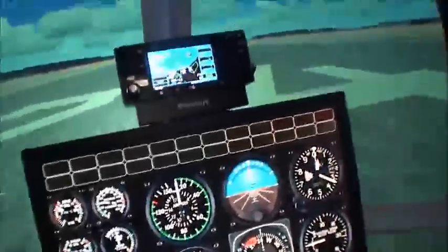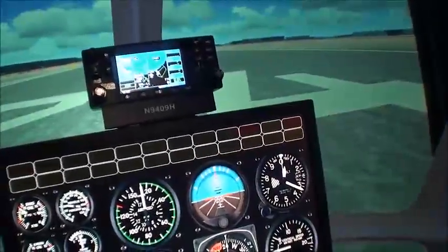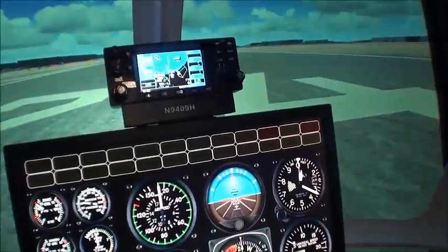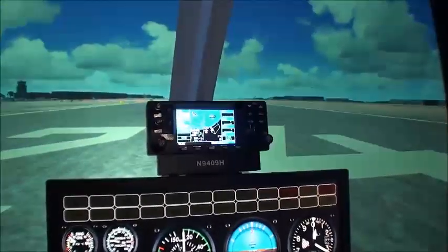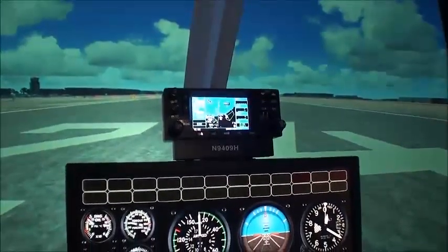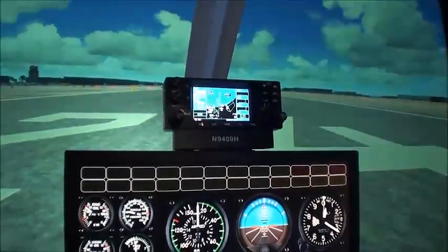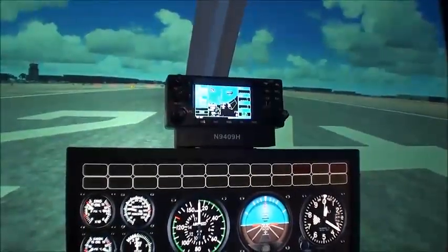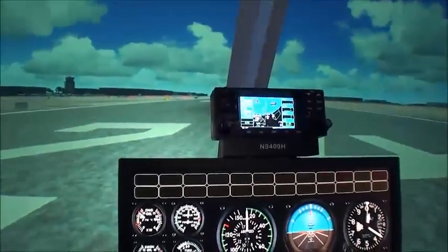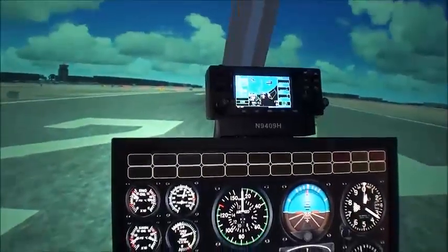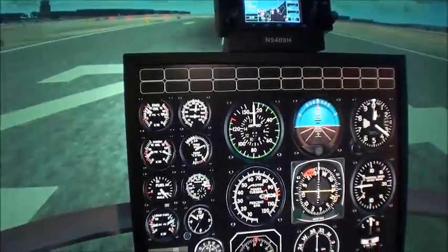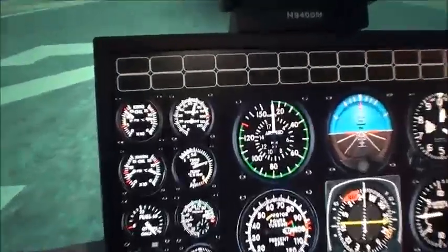Right. The presence and intensity of wind and turbulence must be reflected in the handling and performance qualities of the simulated helicopter. Okay, so Bobby, tell me what we're going to do here. To demonstrate the effects of wind in here, we are going to pick the helicopter up into a hover. So we have 0 wind conditions now, and you notice the torque there, we're hovering around 70%.